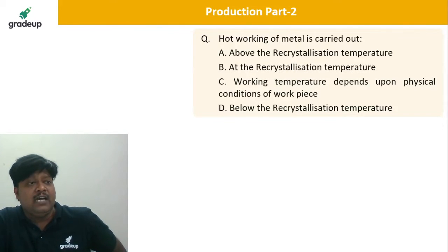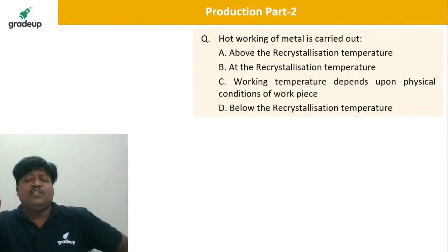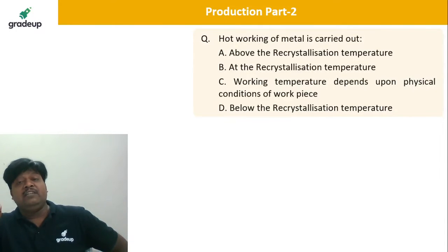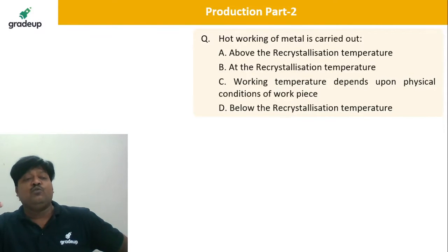Yes, Chinni Anurag, that is a very common thing, dear students. If you are working on the material above the recrystallization temperature, it is known as the hot working process. And when we are straining the material below its recrystallization temperature, it is known as the cold working process. And generally this recrystallization temperature is what?